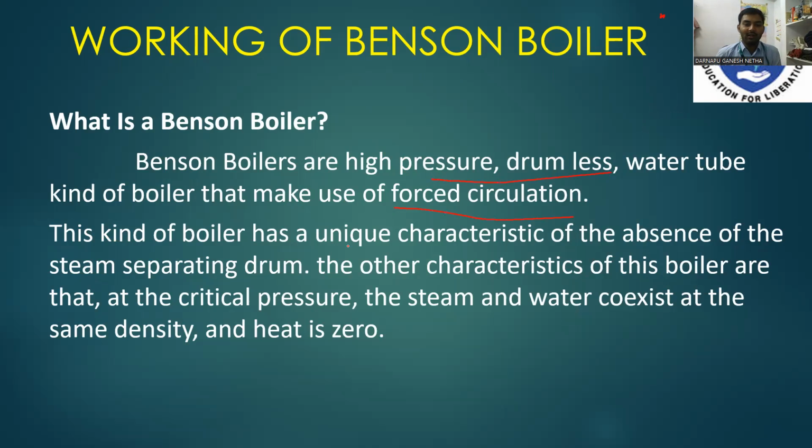This kind of boiler has the unique characteristic of the absence of a separating steam drum. The other characteristic of the boiler is that at critical pressure, the steam and water coexist at the same density, and latent heat is zero.